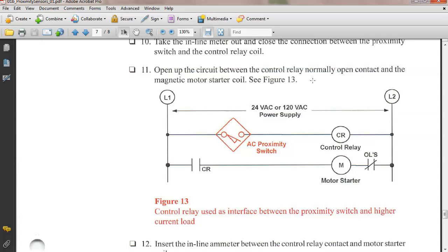It's a 3-pole double throw. So what does the number of poles mean on a relay? The number of contacts that's being controlled, right? You understand that? And then double throw means each one of them's got what? That means they got 2 positions. Everybody understand that? So you got a normally open contact you can use, or you got a normally closed contact you can use. So we have 3 poles on this relay.